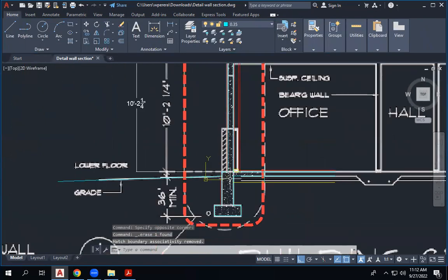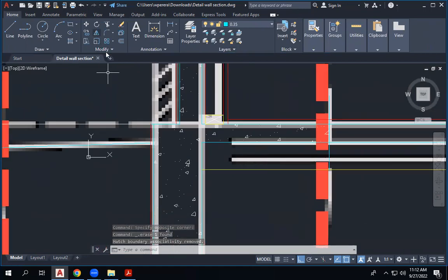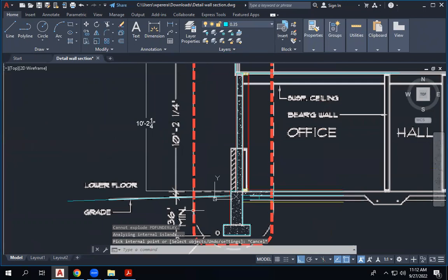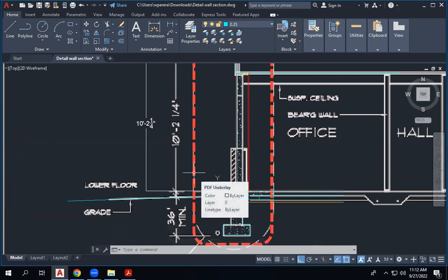I couldn't find the correct hatch. Yes, let's put it there. Okay. And also try to put a hatch here. For the filling, you put a hatch. Every hatch should be 0.0. Don't try to put any thicker line weight for that one because the hatch should be lighter.